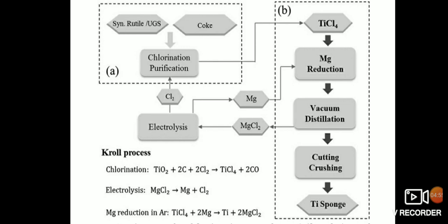In the following treatment, the impurities of silicon, iron, aluminium, magnesium, and calcium, etc., are removed by fractional distillation to generate titanium tetrachloride of around 99% purity. The purified titanium tetrachloride is reduced by molten magnesium between 1075 and 1175 Kelvin in an argon atmosphere to produce sponge titanium, followed by cooling and vacuum distillation to remove the magnesium and magnesium chloride in the sponge titanium.